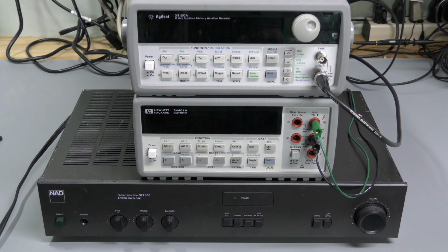It should not introduce extra distortions, and the frequency response should be flat, and so on. And there is also a problem with calibration. The software should be aware of the exact scaling factor to put any absolute numbers on the measurements. Otherwise, we can only look at shapes and do relative measurements.